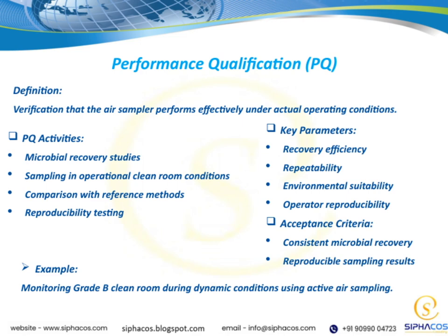Finally, the core definition of performance qualification, or PQ, is that it's a verification process. It confirms that the air sampler performs effectively under real-world operating conditions. This step is vital because it assures us that our sampling process is reliable and suitable for maintaining the integrity of our clean room environment.